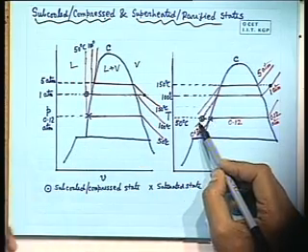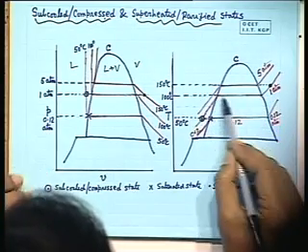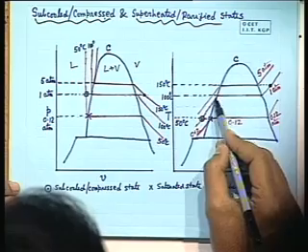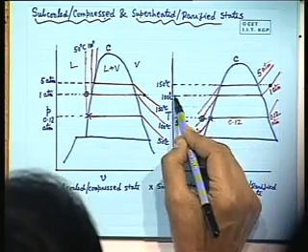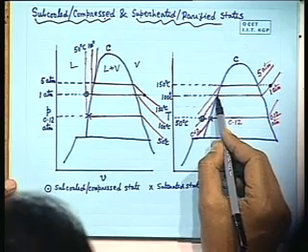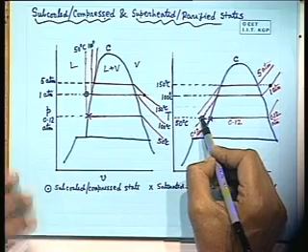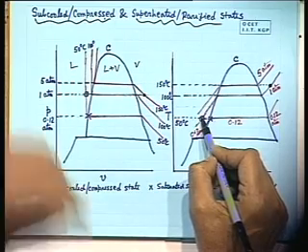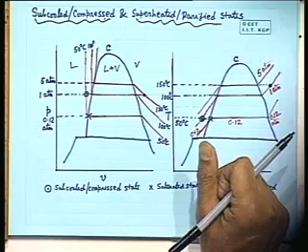So correspondingly in the TS diagram, let us consider that this is similarly the 1 atmospheric pressure line, and obviously this temperature is 100 degrees Celsius. You follow clearly? Now if we have 50 degrees Celsius water at 1 atmospheric pressure, this point is here, that is known as subcooled liquid. Why subcooled?